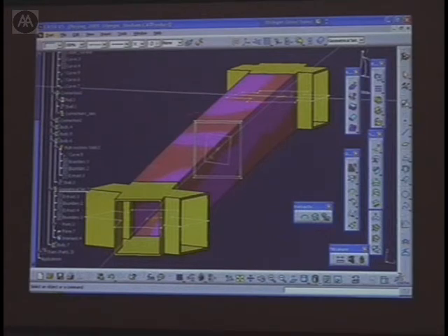That immediately means that if you're going to have tangential joints, you're going to have a torsion in the beam. And torsion in the beam is very, very complex to achieve when you're double curving a steel box girder like that, that weighs 18 tons and is 50 millimeters thick. So you say, well, how about we don't have a torsion? What about if we just have curved in one direction so that this side is flat, the other side is flat, and it just kind of goes like that?